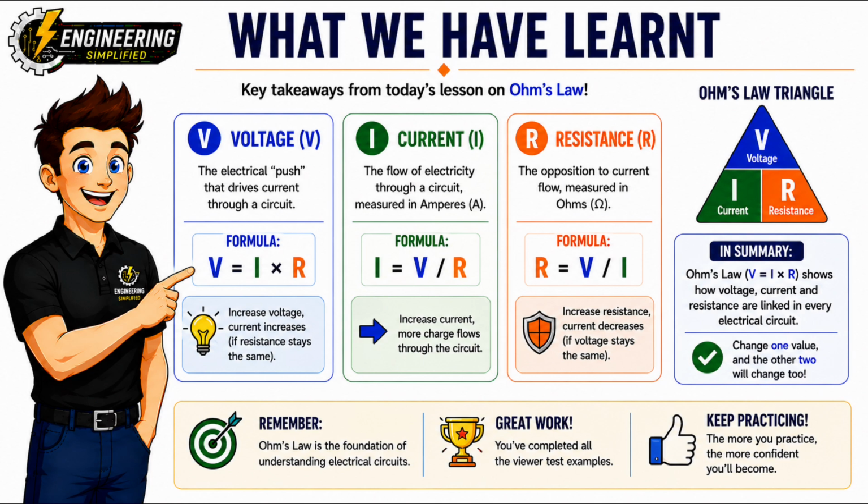We've also seen that increasing voltage increases current when resistance remains constant, while increasing resistance decreases current when voltage remains constant. Ohm's law is one of the foundations of electrical engineering, and once you understand the relationship between voltage, current, and resistance, you have a powerful tool for analyzing electrical circuits.